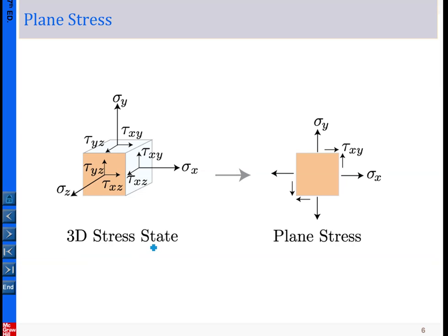So this is three-dimensional and nothing special. For the plane stress, that means when the z components, this one, and then this one, basically this is equal to 0, this is equal to 0, this is equal to 0. When the three stress elements in the z-plane become 0, then you can simplify the schematic drawing into this case. Okay.